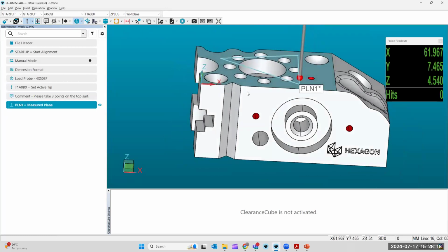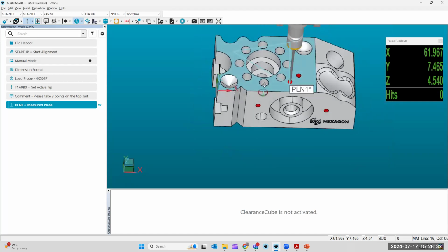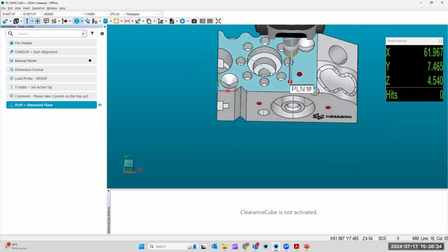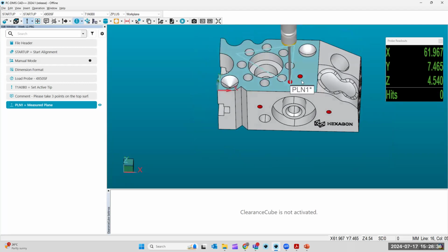When I do a 2-dimensional alignment, my line has a dependency on the previous 3-dimensional feature. This is about how probe tip compensation is going to work, because in our CAD model, everything looks perfect, but in real life, our part's not perfect and our planes might not be perpendicular to one another, or it might not be aligned to our axis perfectly on our machine.